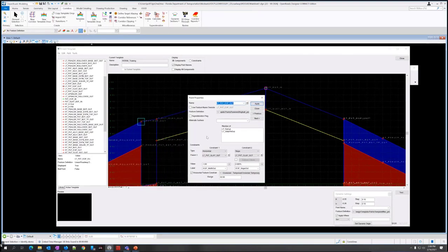Double click the LTPVT EOP underscore out. This value is going to go from -1 to -0.01. Sorry, to -0.01. Gotta keep that negative in there. And the horizontal constraint, we're going to set that to 100. I'm also going to make sure this is the right constraint. Pavement asphalt UPA. It's under the linear roadway design plan profile 2D lines pavement asphalt UPA.